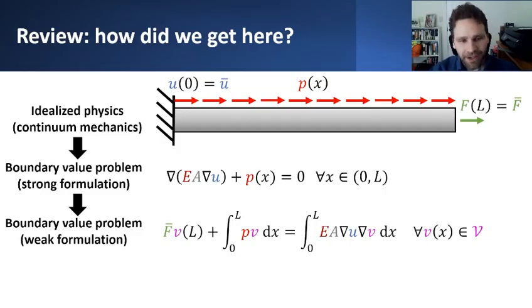and that alternative format happened to be the corresponding weak formulation of the equivalent boundary value problem expressed in strong form. The weak formulation was really nothing more than a statement of virtual work, in analog to a lot of classical principles in structural analysis. But the basic idea was that we could take this pointwise statement of equilibrium and convert it into an equivalent integral average form of equilibrium weighted by some additional test function or virtual displacement function.